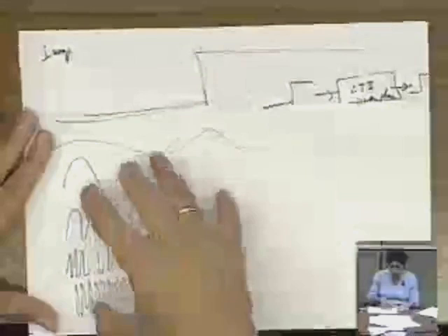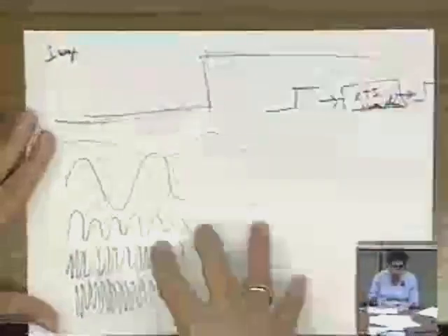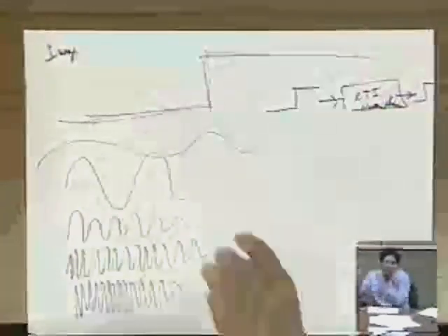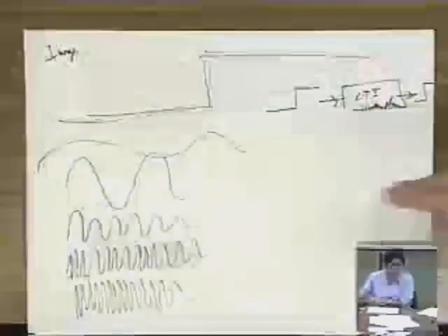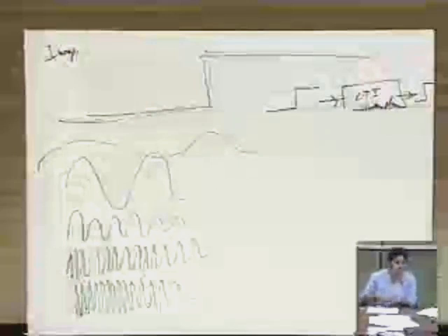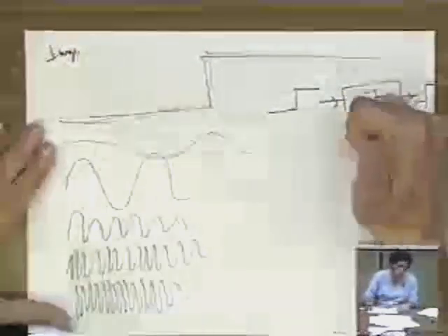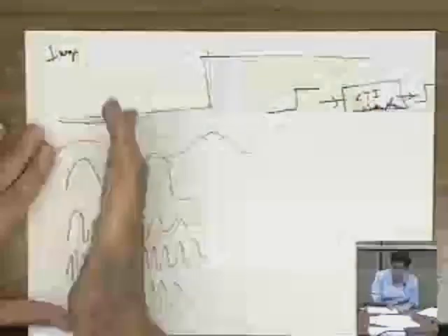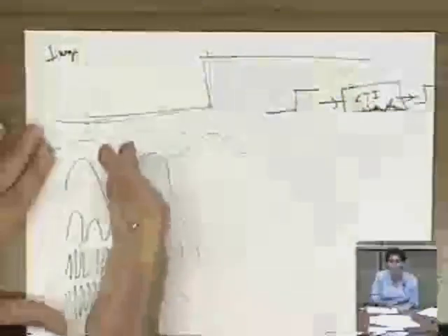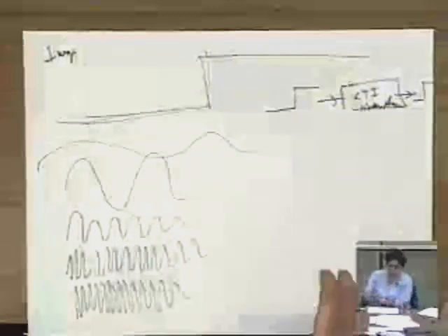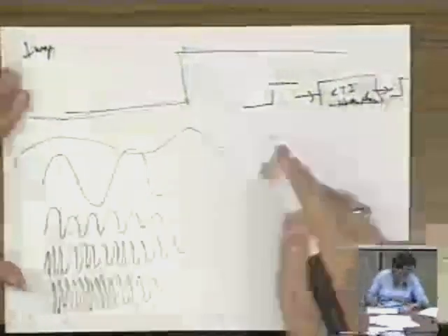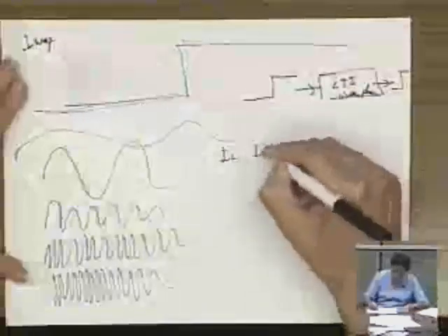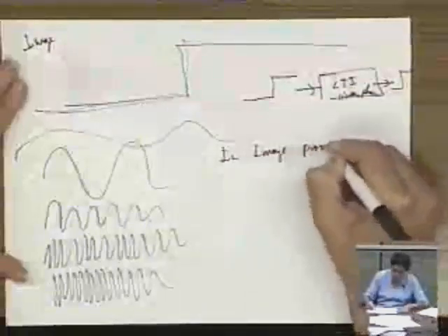And so if I pass it through a linear phase system where the group delay is constant, where each of these sinusoids that constituted this thing got delayed by the same amount, they have the same phase relationship at the output that they had at the input, because each of them got delayed by the same amount. My LTI system was linear phase, and it just purely delayed each of them independent of the frequencies. So when I add them up, I get the same edges I had before.